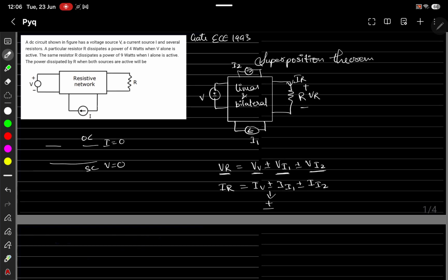Actually in this problem we cannot comment, but if you know what is inside this network, we can. If voltage sources are arranged like this, now I am traveling in this direction. You jump and look back, what will you see? We will see a positive sign. Let's say this is V1 and V2. We jump and look back, what do we see? This is positive. And again we jump and look back, what do we see? We again see positive. So again plus V2. Here both V1 and V2 are supporting each other, so we will add these voltages.